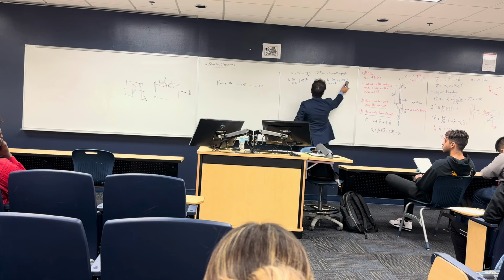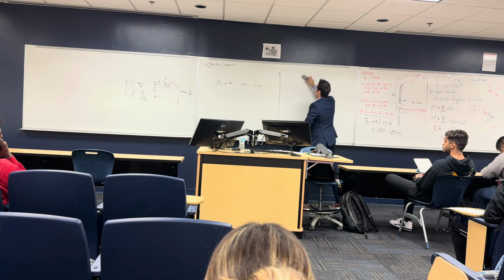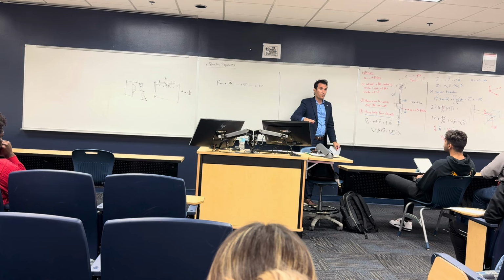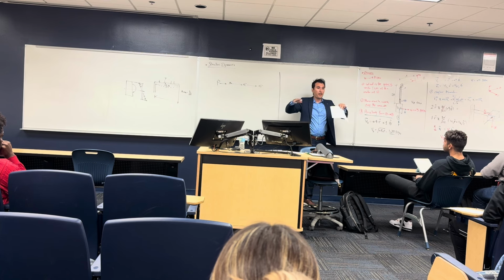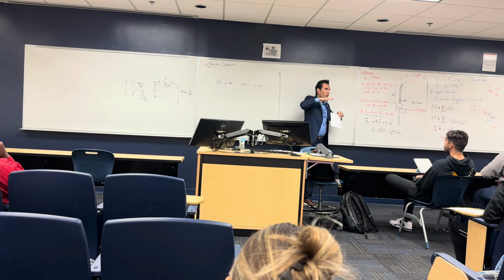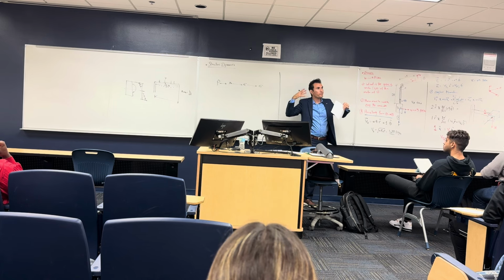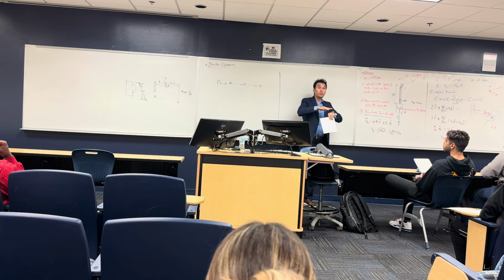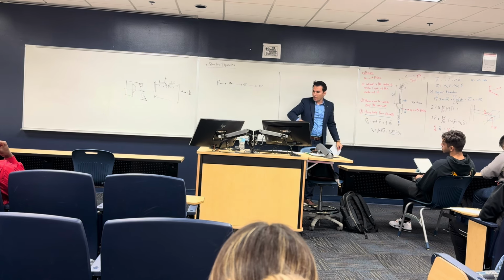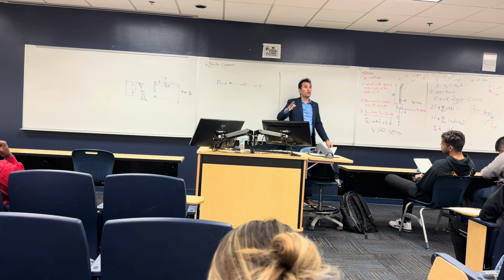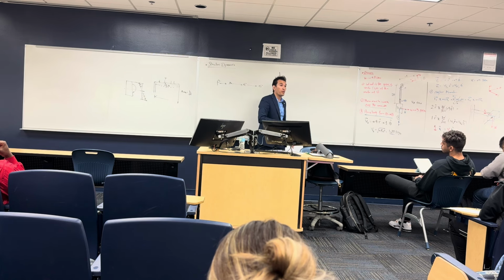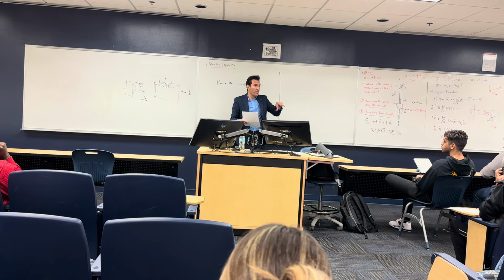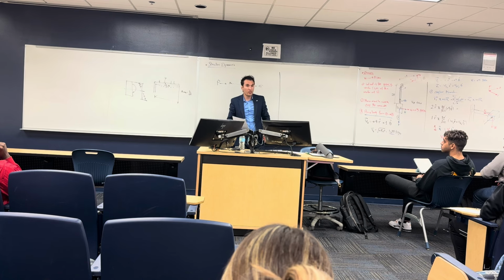But with structural dynamics, when I gave the example of this floor, all our loads right now are static loads. Even though we are moving, with the way we designed this floor, we calculate all our weights. Let's say everyone averages 80 kilograms. When we get all the weights, say 100 multiplied by 60, so 6,000 or 10,000 kilograms, like 1 ton, we distribute it by the floor area, and every 1 meter by 1 meter gets 100 kilograms per square meter. This is how we distributed our live load on this floor.